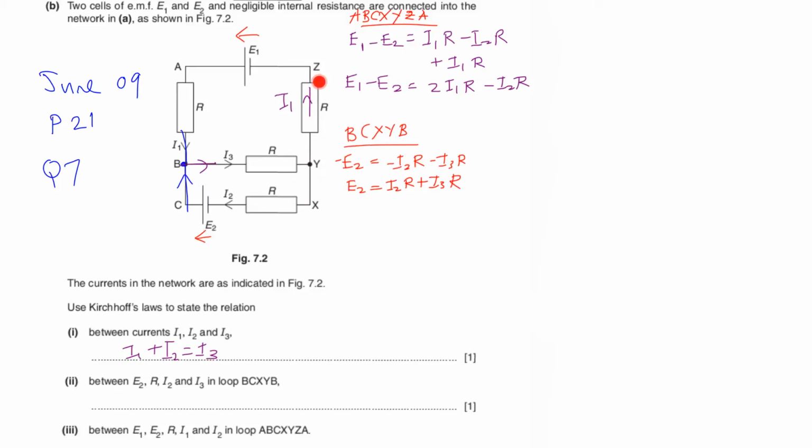Then we come to this resistor, we are going up. Current is what? Now, some people get confused about the current here. They thought the current is I3 or I2. How to determine the current is you must look at a series circuit where there are no branches. That means there's no way the current will split. For example, if you take this current, there's a branch here. If you take this current, there are branches here. So you cannot take the current here and here.